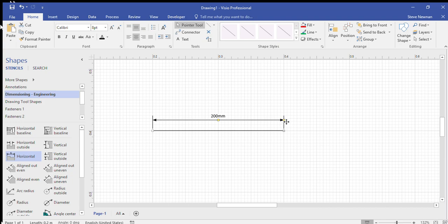To increase the dimension lines here, I can increase, decrease those. If I want to move a number somewhere because it's in the way, use the other yellow box. Now, I said it wasn't 200, I said it was much, much smaller. So our size for the top of our spinning top is 8mm in diameter. So let's drag this, let's leave that there.